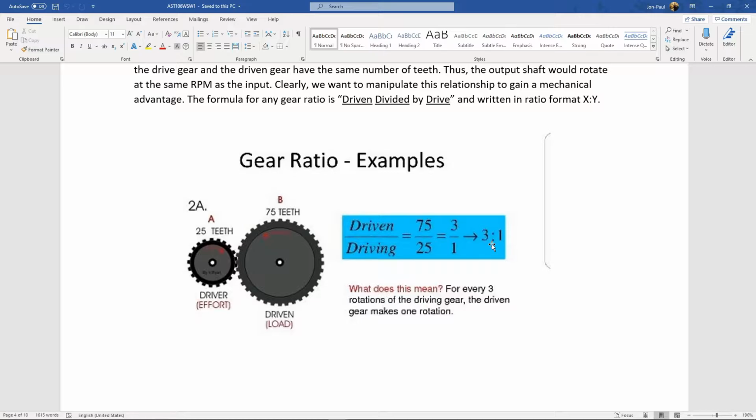A 3.73 to 1 gear ratio. And then you want to change it because you want to go faster on the drag strip, so you put a 4.11 to 1 gear ratio rear end in it. What will happen now is you will accelerate much faster and you will lose top end. You will not be able to achieve a high speed because you've traded now greater force for less distance.